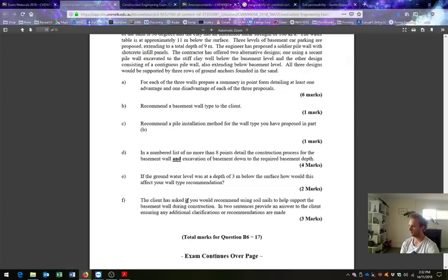Okay. What's the difference between the serviceability capacity and the limit state capacity for bored piles and CFA piles? I think what you probably should do is look at the formulas that are used to calculate the capacities and the variables that are going into those formulas. For example, phi g is used in limit state, but it's not used in serviceability. Additionally, the end bearing capacity is used for limit state, but it's not used for serviceability. So that will give you a feeling for what factors are feeding into it, and then you need to look at what affects those factors. I know it's a bit of a general answer, but I hope it makes sense.